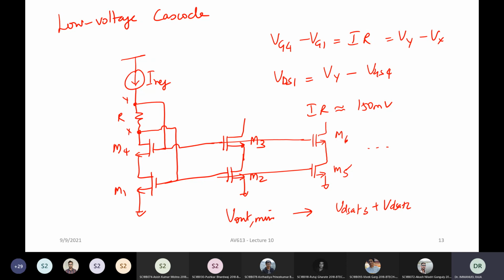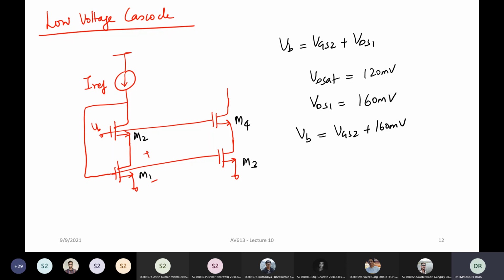Now you might build in some margin for the sake of process variation and things like that. Just a little bit of margin. You don't always put it exactly at VDSAT. Maybe just give it a little margin, like how I showed you here. Right? My VDSAT is 1 millivolt.